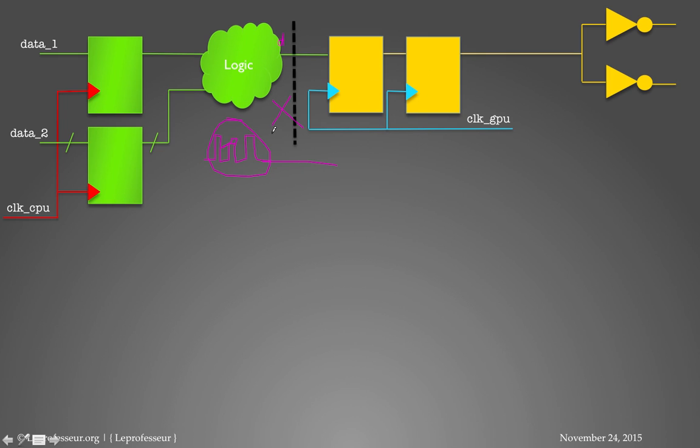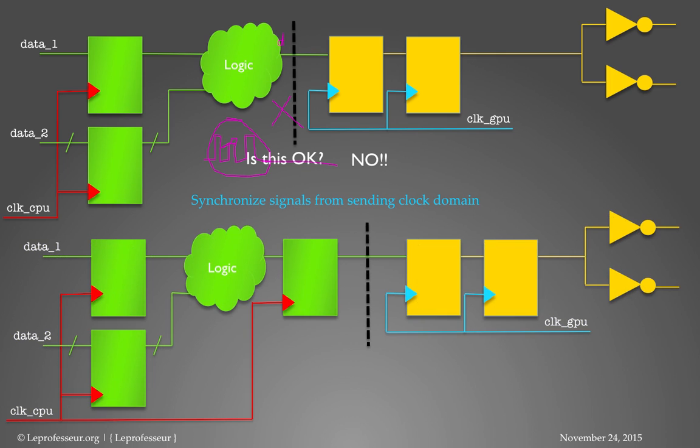So that increases the probability of failure. Okay. So the best idea is to register or synchronize the signal from the sending clock domain to the receiving clock domain.